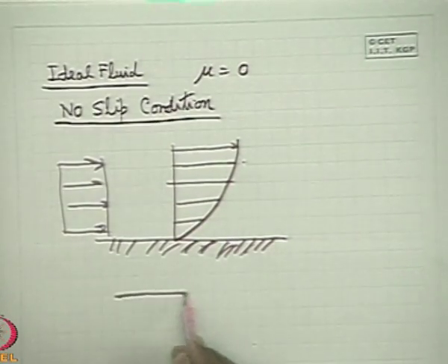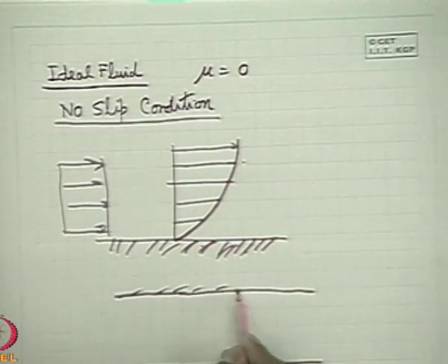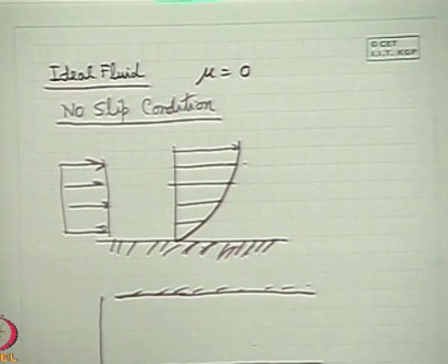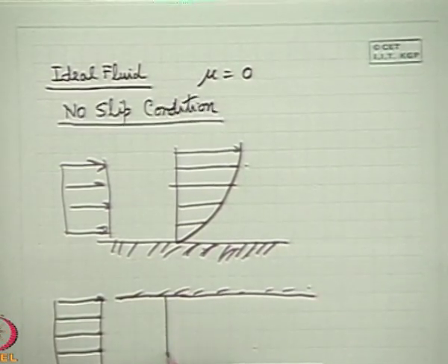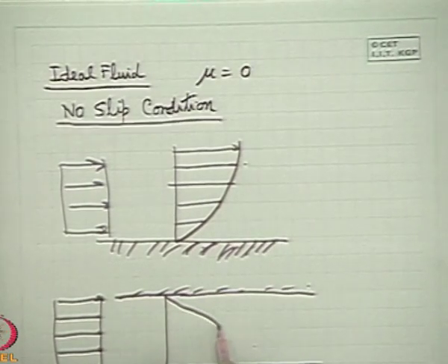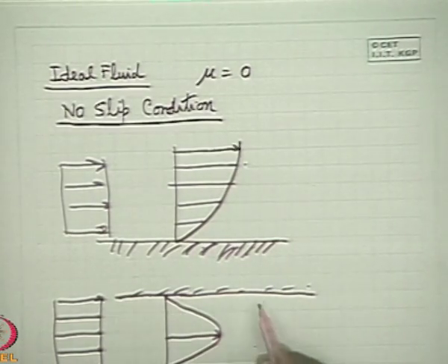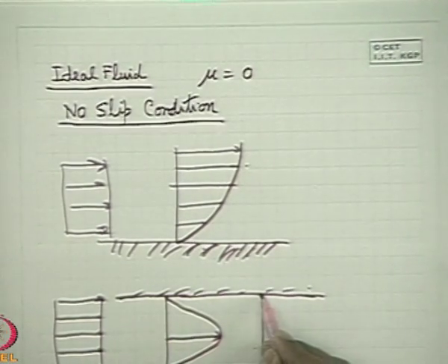Similarly, in a pipe flow, I just give you the picture, which will be taught in detail afterwards. In the case of flow of fluid through a pipe, if the flow approaches first with a very high, uniform velocity, whenever it comes in contact with the solid at any section, the fluid velocity will be like this. There will be a distribution. A maximum velocity usually occurs at the center. So the velocity at the solid surface will be 0.